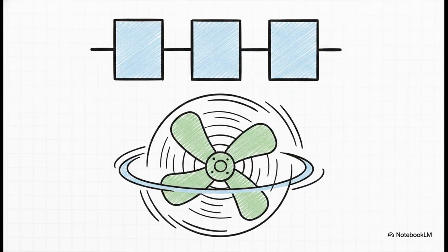The really crucial thing to know about PWM technology is that digital microcontrollers, like the ones on your computer's motherboard, only really speak in binary, on or off, 0 or 1. So to control an analog fan smoothly, they use PWM. They send incredibly fast, super short pulses of voltage. By modulating exactly how wide these pulses are, they simulate a smooth analog speed.